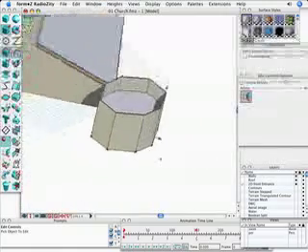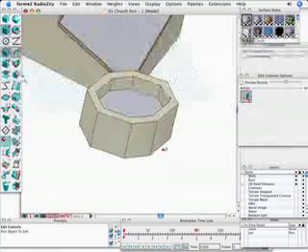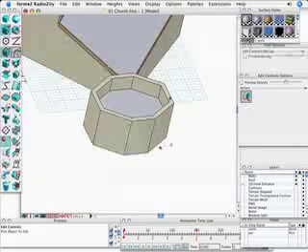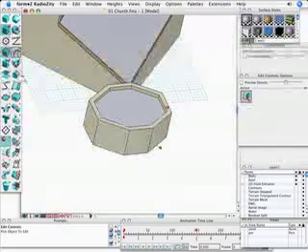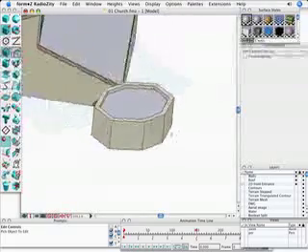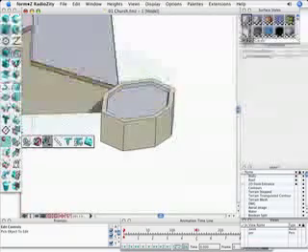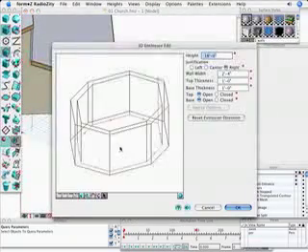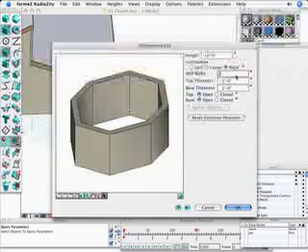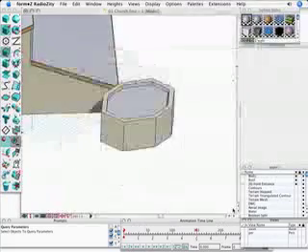Now, whether the geometry is created directly or created using the derivative tools, we do have access to the control parameters to further modify it later. So you can see here, I can graphically modify the wall thickness and height and shape of that geometry by graphically moving those controls, or we can query the parameters in which we can numerically edit all those same parameters that we were changing graphically.